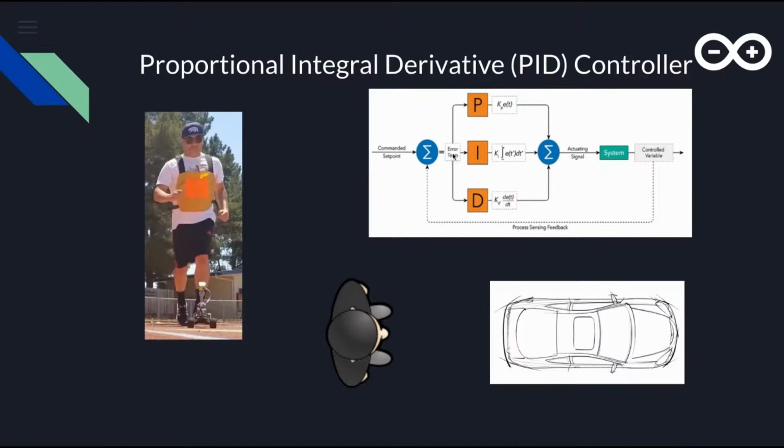where the error term gets calculated. When the person is standing right behind the robot, the error term is 0. So it gets multiplied with the P, I, and D variables independently, which then get summed up. This result gets sent to the control variable, and this allows the robot to know whether to turn left, right, or continue moving forward. Also to speed up and slow down.